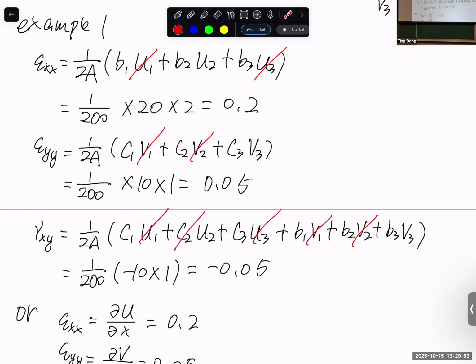So I really want to say that as an engineer, your job is not to go for perfection in every detail. If you keep all the details, like the small holes and small points everywhere, you will not get final results. In this project, as long as I keep the shape here, I know the maximum stress is around this location.